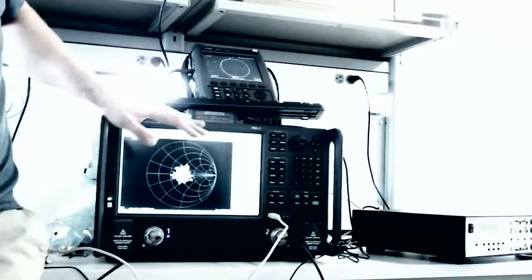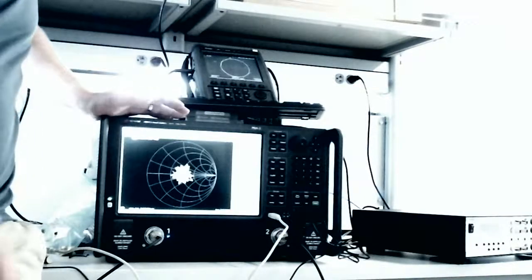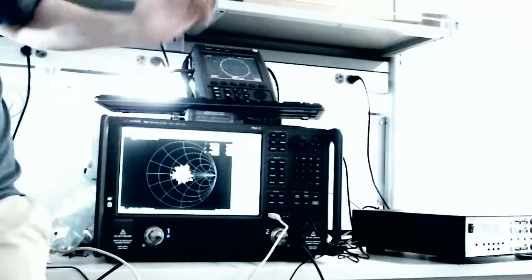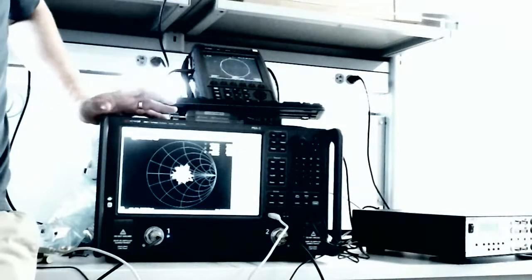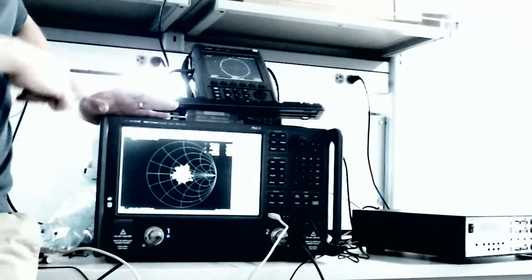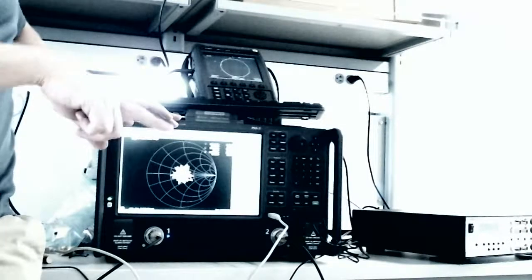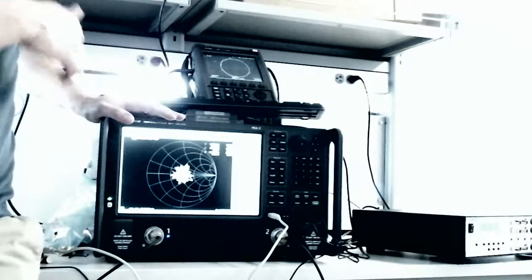Or you can do this and then say, I want it at 5 or 10 different frequency points, and then I can just use the marker, and every marker that I put in, I can change the frequency and say, I would like to know at 5 gigahertz, at 1 gigahertz, right? And now I have R plus JX at all those different points. So it depends on what exactly you want to do. If you just want to see a plot of R versus frequency and then a plot of JX versus frequency, you can do that. You just use the equation editor, use S11.